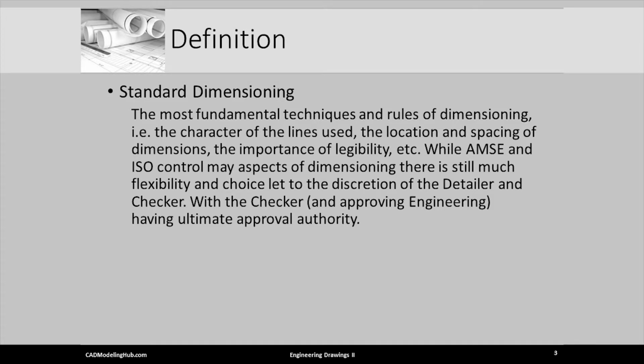What do we mean when we use the phrase standard dimensioning? We mean the most fundamental techniques and rules of dimensioning, such as the character of the dimension line, the location and spacing of dimensions, the importance of legibility, and so forth.